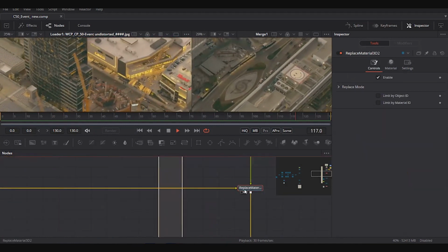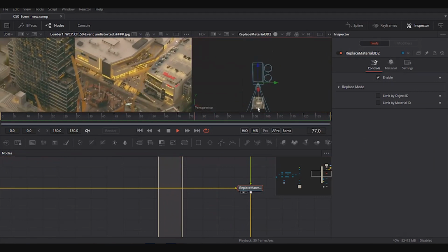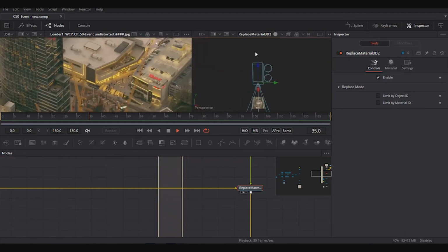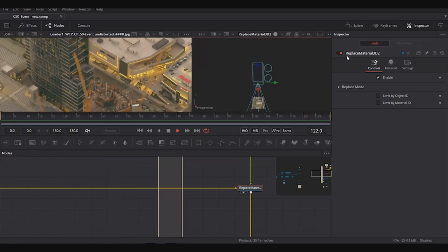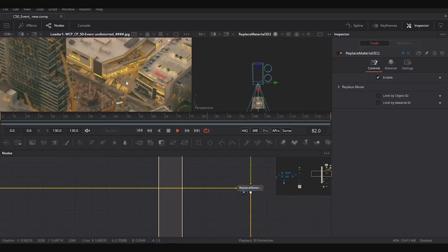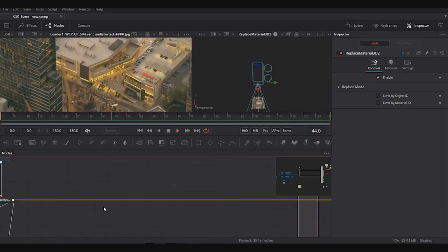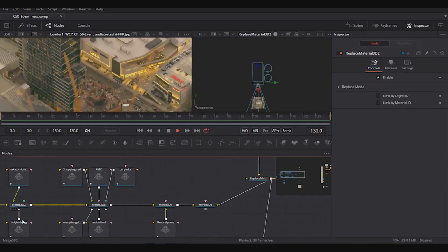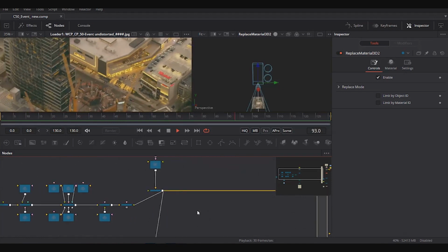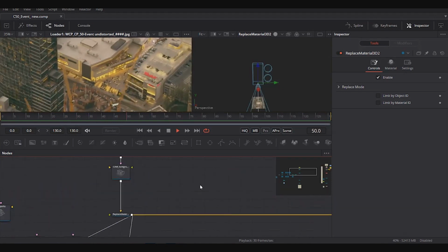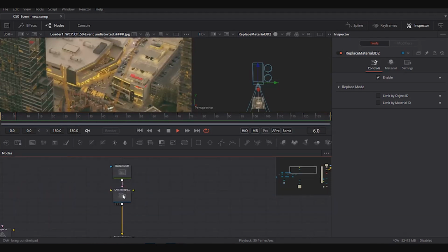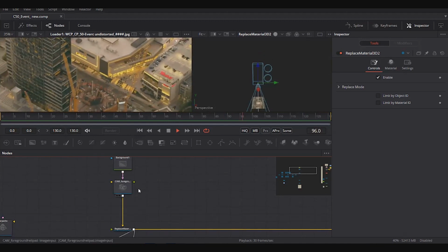The technique we covered involved a single plane catching the footage, observing the plane from this camera, working on it, and then viewing it from the moving camera again. This has a lot of varied surfaces. Rather than catch it on a plane, we're going to catch it on geometry. And now you're going to see why the context model being split into layers was so important. We're going to set up image planes with cameras, but then we're going to swap the geometry.